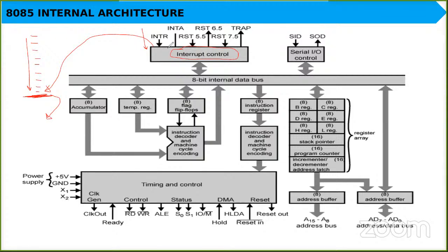It's an interrupt which goes to the processor and tells it that it is time to wake up. The system is sleeping, using minimum resources, and suddenly an external device gives an interrupt. That external interrupt produces some reaction, and that reaction is determined by the program. So interrupts are required to interrupt the actual execution of the main program.